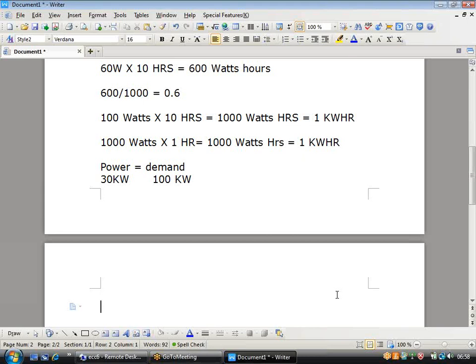But generally, whatever consumption happens for 15 minutes continuously, that is most important. So if both these machines are going to run for a minimum of 15 minutes interval, then two different power ratings are coming. One is coming as 30 kW, one is coming as 100 kW in the usage of 15 minutes. Then when the electricity department is going to bill, they are going to build the tariff structure according to the power rating. If your instantaneous consumption for less than 15 minutes is going to be less than 30 kW, then whatever consumption you are doing, it is going to be charged at 5 rupees.